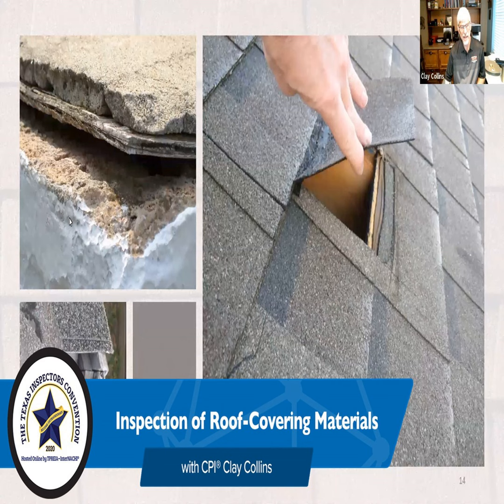What else? Okay, and what roof pitch is considered to be too steep to walk on? Remember that picture where I pointed to the guy standing on the very top? That's going to be a call you have to make. A lot of it depends on what I have that I can hold on to when I'm going up there. But if you want a safe answer, it is anything more than 4/12.